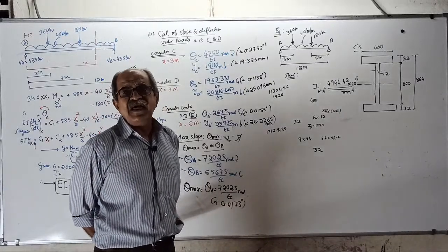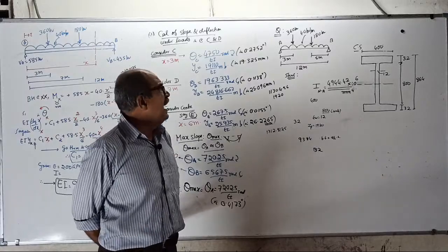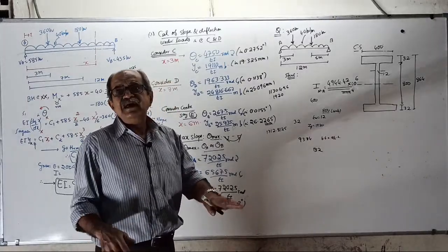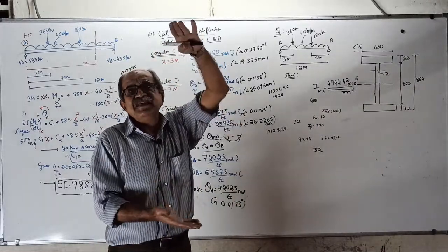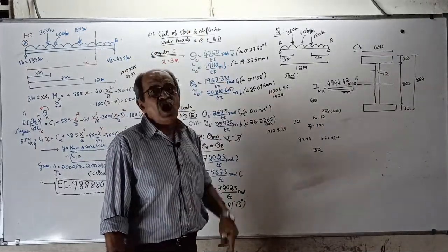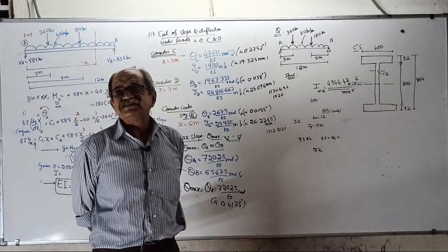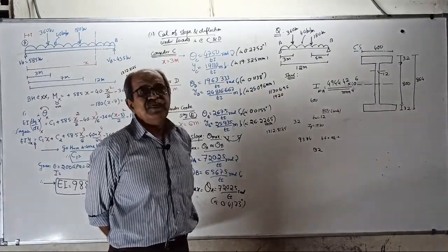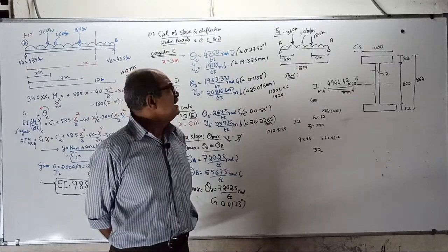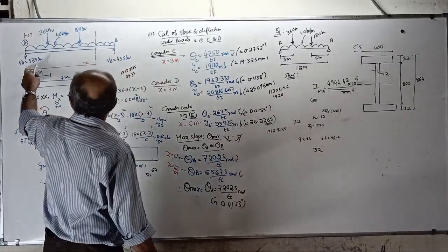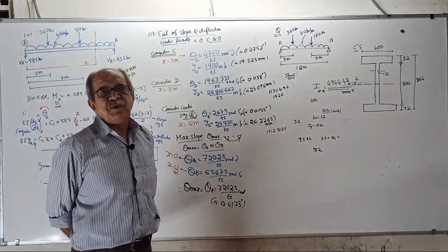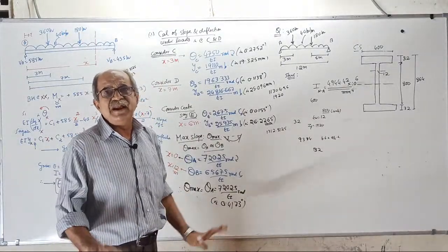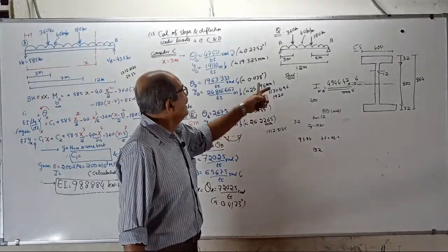I factored that load and then provided an I section for the beam, with flanges and web fabricated, not RSJ, not ISMB, because even the highest RSJ available is not sufficient. It's a very heavy girder, so the requirement of cross section is very high, so a fabricated section. I will tell further in the question.